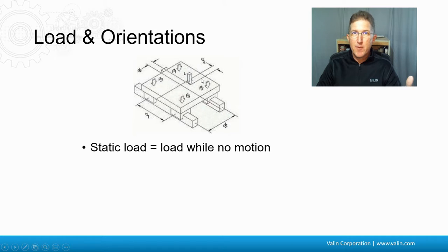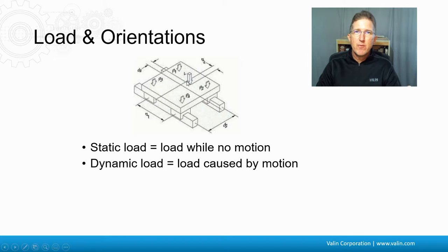So we'll talk about static loading sometimes, which is the load while there's no motion. So just sitting here, this 1 pound is 1 pound down on the stage. But while it's moving, that can cause a dynamic load because the mass times the acceleration can cause a force.